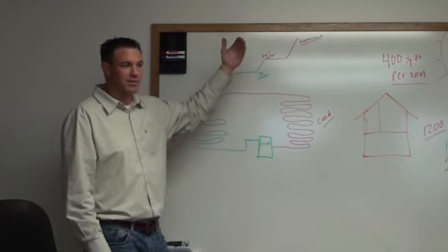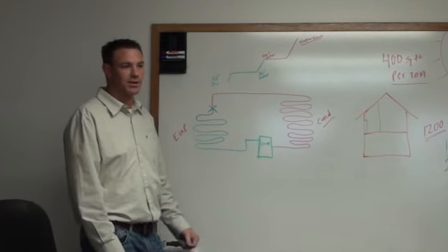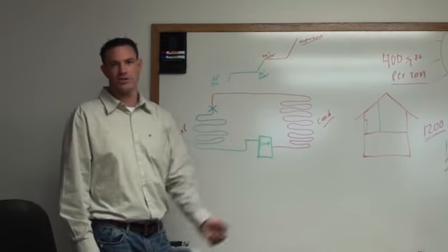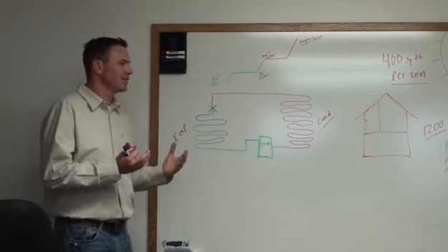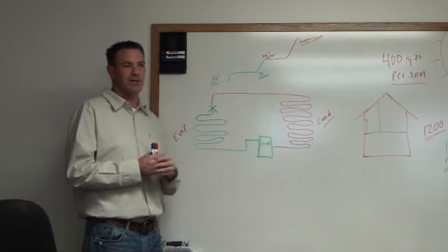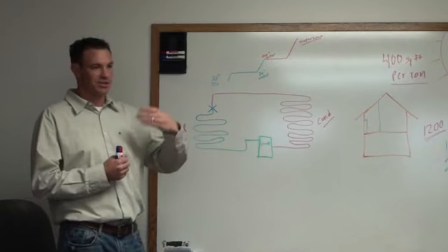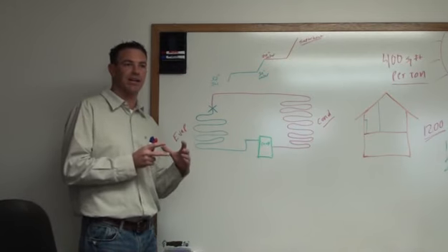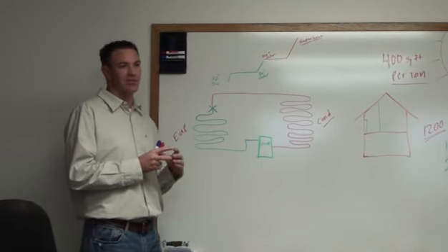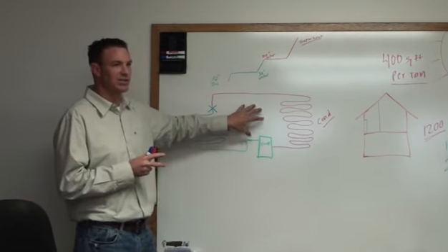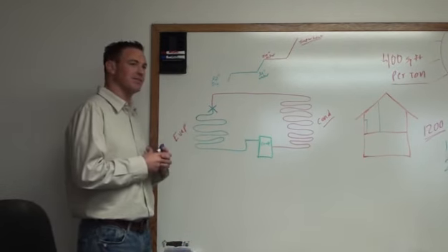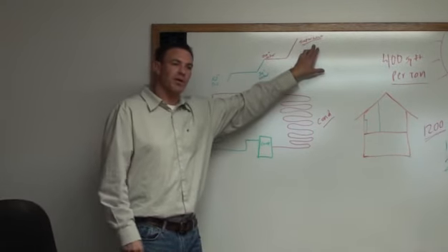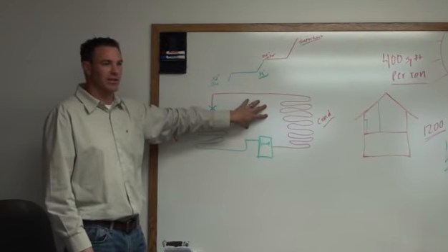Above and beyond 212 degrees, we can get hotter than 212 degrees. We just add a little more latent heat. We'll change state, and then we do what we call superheat. That would be similar to, you know, if you guys remember your mom putting peaches or something like that in a pressure cooker. That's how she got that temperature up there, by adding superheat. And it's because that was contained in its own atmosphere. The way you contain superheat and use it in our application is you put it all in its own atmosphere, and it becomes its own entity at that point. So superheat is a very important part of what we do in the heating and air conditioning industry.